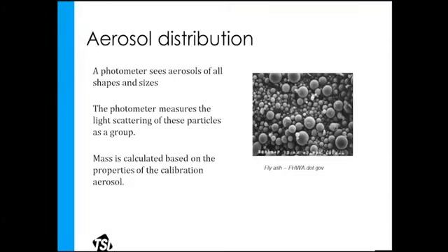So to get that calibration factor, we can do a side-by-side measurement where we measure the mass. Again, don't throw the pumps away. Measure that mass on the filter. At the same time, you've run the DustTrak, and now you compare the DustTrak number to the gravimetric number. You take the gravimetric number on top, divided by the DustTrak number, and that's a calibration factor.